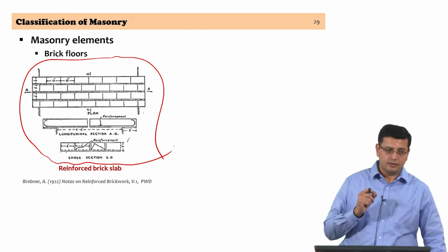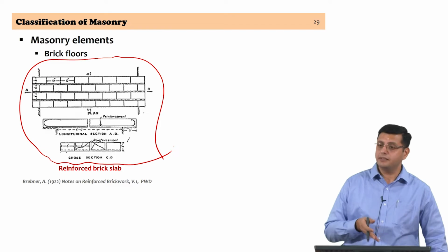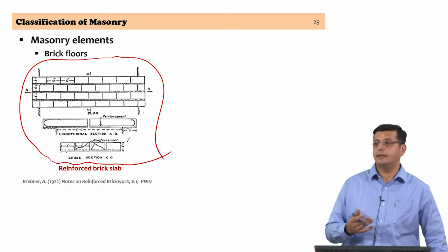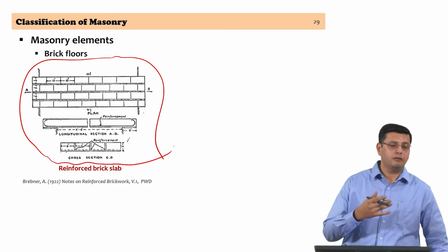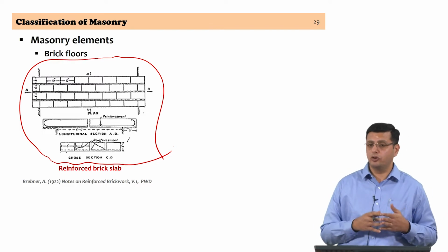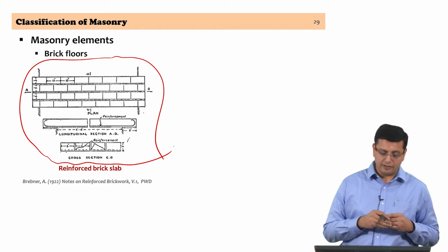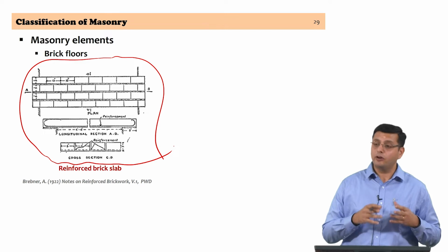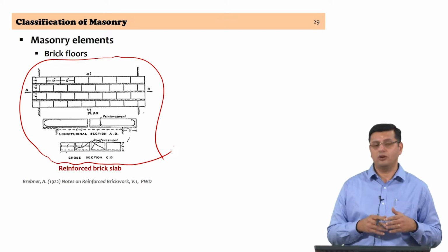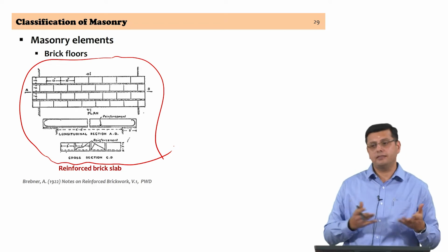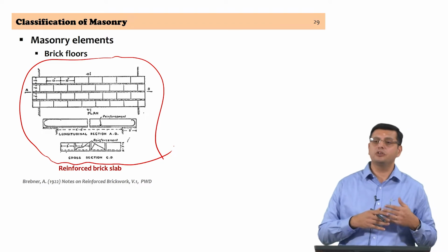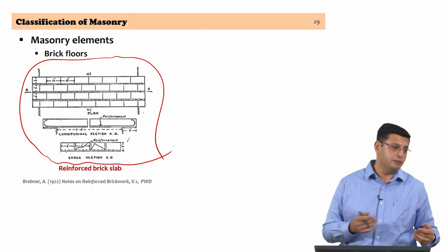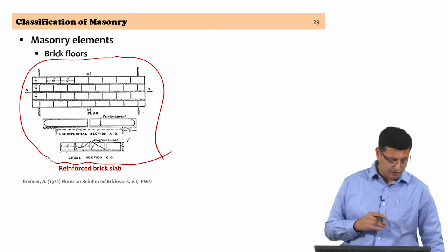Once the steel that is present in the brick slab starts corroding, the brickwork starts spalling. Unlike concrete that spalls, where you can repair a reinforced concrete slab that is affected by corrosion with spalling and other effects, repair of a brick slab is very challenging, because replacement of parts as a patch repair is not something that is simple. So, in situations of excessive corrosion damage, replacement of the slab is the only option that you would have.